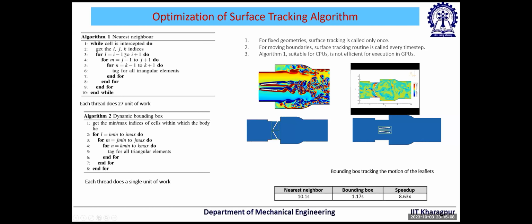Instead of tracking for each of the fluid points, if we use a tracking based on the solid surface points using a bounding box, we can reduce the computational time further by 8.6 times. And this is a more GPU friendly search algorithm.